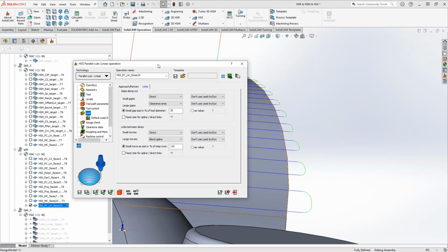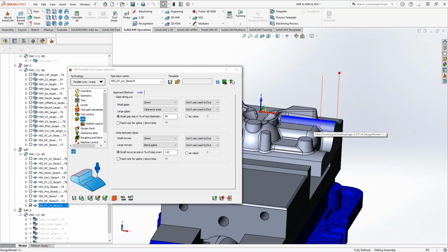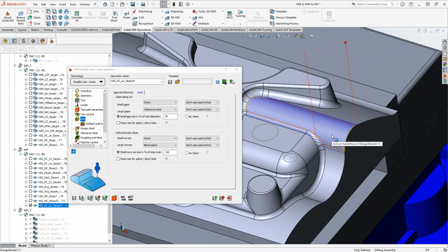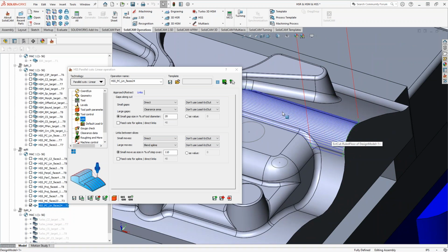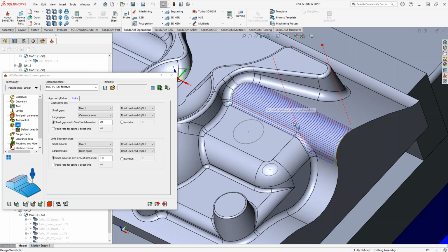And that's pretty much the point of HSS. It's a finishing toolpath. You want to make sure that finish is good. You eliminate any kind of witness lines or any kind of indication of a change of direction. One of the recommendations, at least on my side when I train people, is you want to make sure that you break up your part into the different surfaces so that you don't get a lot of weird jerky motions, a lot of weird looking toolpaths. If you break it up into the different surfaces, you get smooth looking toolpaths where they need to be.